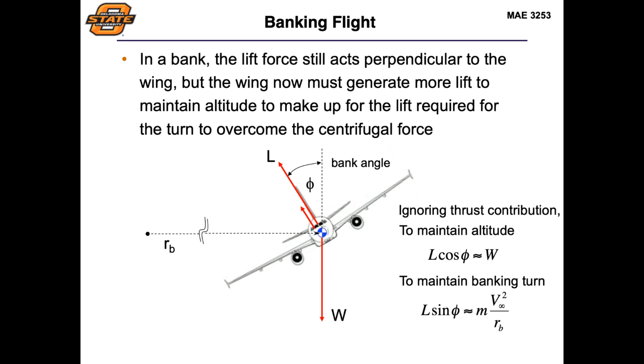So we're increasing the angle of attack, so we're still able to maintain a level flight altitude. So we're essentially performing a coordinated turn for our aircraft, where we have a radius of curvature associated with this turn, but we're no longer ascending or descending within our particular motion of flight.